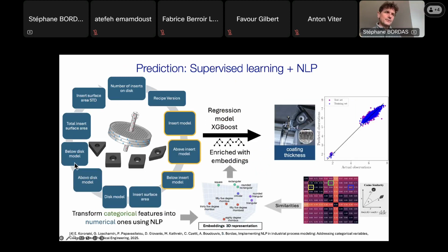Let's say that you need to vary each parameter, take 10 values for each parameter. You have 12, that's 10 to the power 12 combinations that you need to look at. So 10 to the power 12 is much too many, even if you have a surrogate model for each simulation that is going to give you some results in 1 second. You still have 10 to the power 12 simulations to make, which is 10 to the power 12 seconds, still far too many. So you're not going to be able to optimize the system, right?